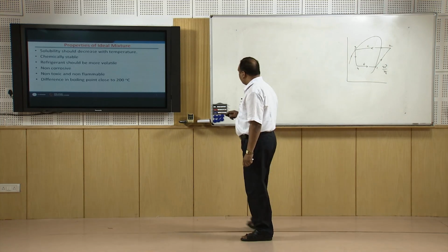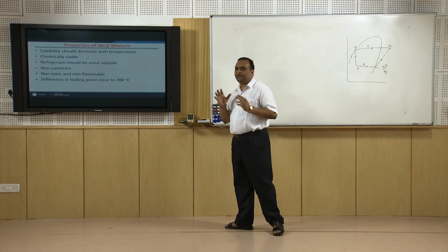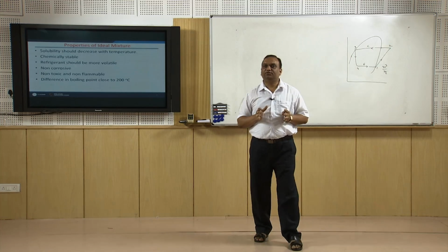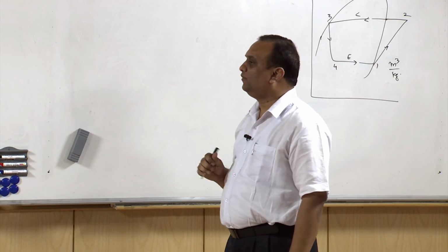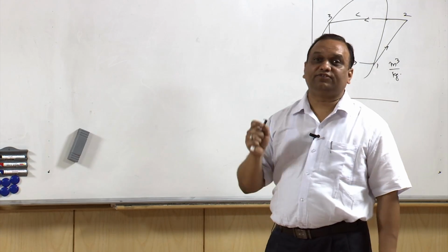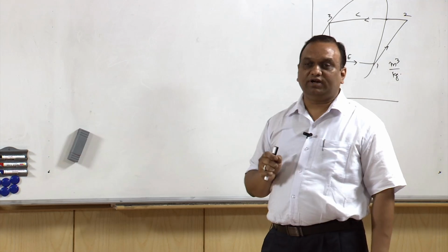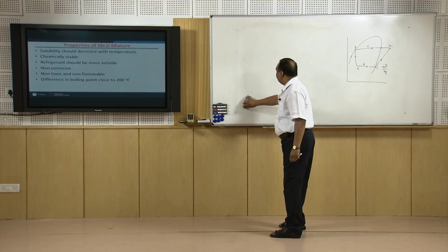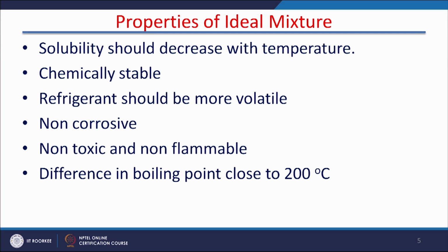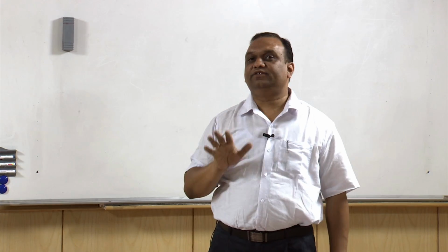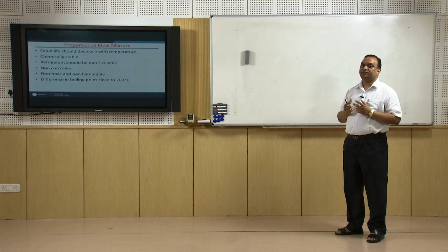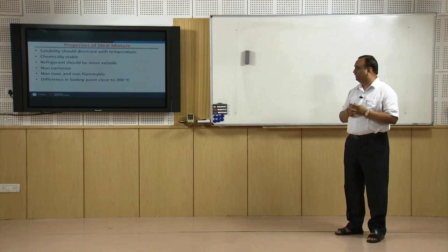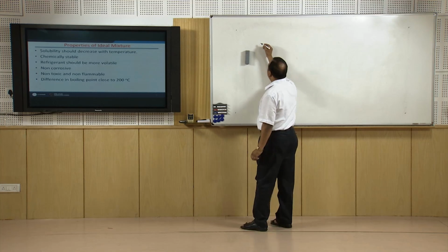Now, we will come to a different type of refrigeration system, which is known as the 3-fluid refrigeration system. This system was developed by two undergraduate students at KTH Sweden. In this system there is no moving part, it is a completely silent system, and pressure in the evaporator is controlled with the help of hydrogen. Hydrogen is another fluid. So, it has 3 fluids, that is why it is known as the 3-fluid system.